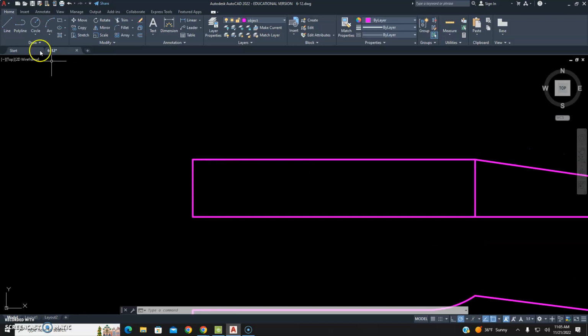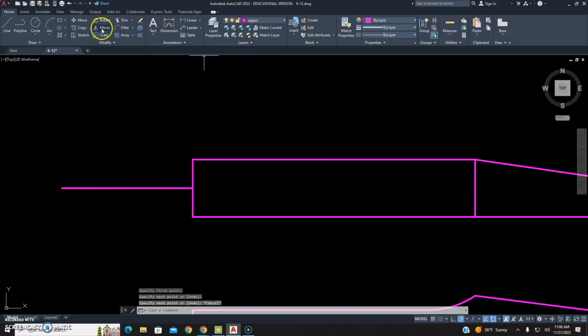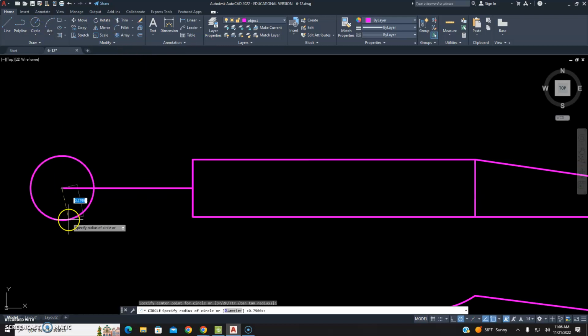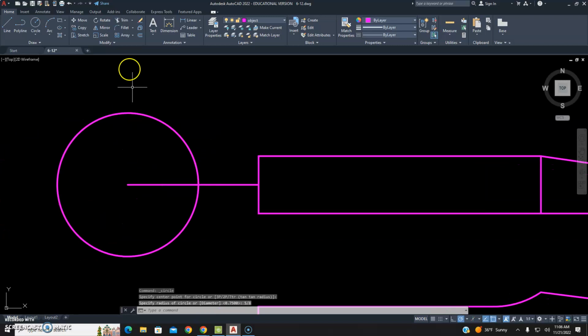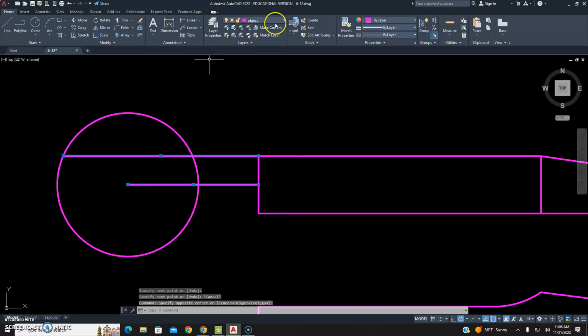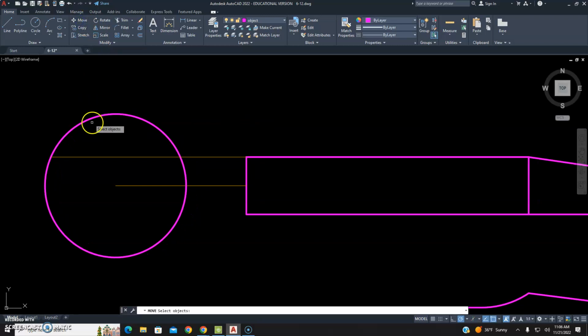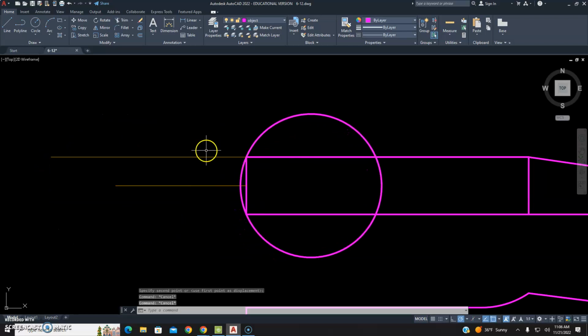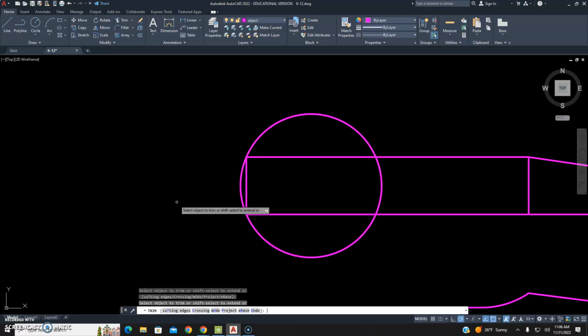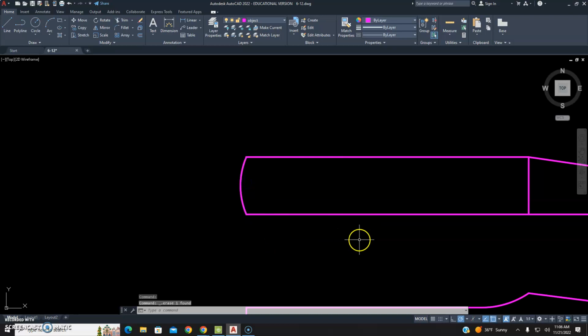Again, that's going to go here. We need it centered up, so we're just going to draw a line straight out from the midpoint here. And then we'll draw our 5/8 inch radius here. Circle. And then we can bring another line out. And again, you could do this in construction. In fact, I'm just going to change these really fast, just that way it's a little less confusing. And we'll just use the move tool, select our circle, and grab this and bring that over. Delete these, and then trim. 1, 2, and 3. And then we can actually get rid of this line too.